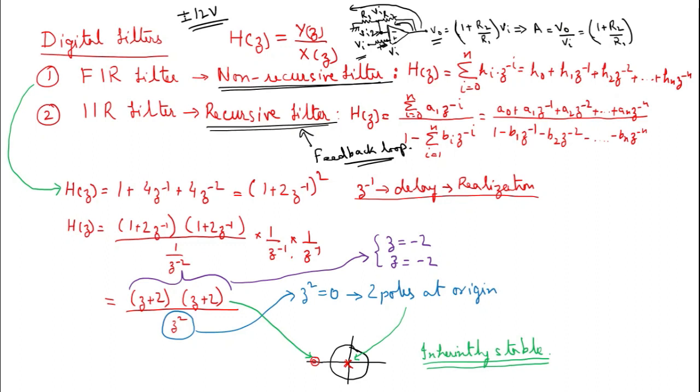Most of the op amps. There are certain op amps which can be powered by plus minus 5 volt power supply. Some may be powered by plus minus 15 volt. But under normal laboratory circumstances, most of the op amps are powered with plus minus 12 volt power supply. And when we operate the op amp using a plus minus 12 volt power supply, the operational range of the op amp is usually 2 volts lower than the supply voltage. So that means the operational region is within the region of plus minus 10 volts.